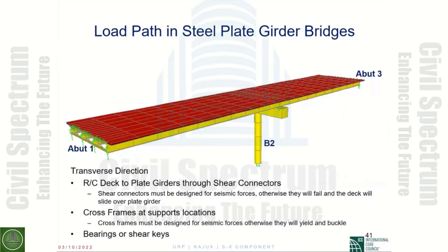Load path in a steel plate girder bridge, as I told you before: you will have the RC deck. You will have a composite construction. So the forces would go from the RC deck to the shear connectors or shear studs, and then from the shear studs to the plate girder. Please pay attention to